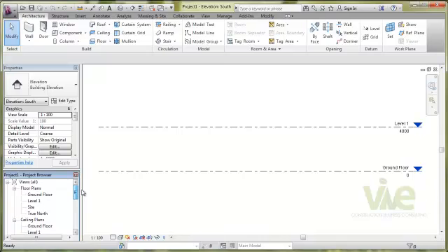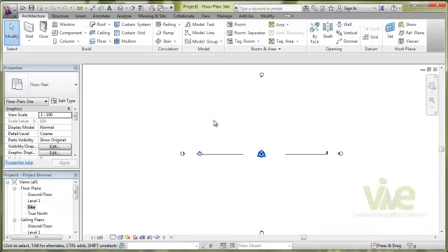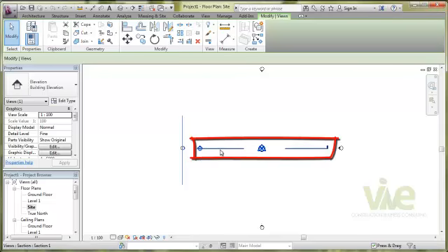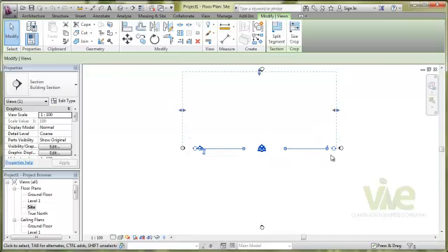So let's go into our floor plan. We're going to open up our site floor plan. A couple of things to consider in this view. We have 4 little circles with an arrow at the end pointing inwards. These are our elevation views. We also have this section view line at the center, which indicates that there is a section view right down the middle of this view. This dotted line around the section icon represents the far clipping, the extents that we can see in our cross section.